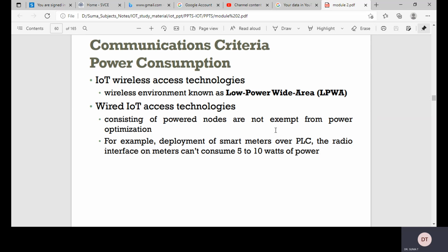The two main worldwide sub-gigahertz frequencies are 868 MHz and 915 MHz. However, parameters such as transmit power, antenna and EIRP must be properly designed to follow the settings required by each country's regulations, whether it is India or Europe, whatever it may be. We must be very specific when we deploy these kinds of things.